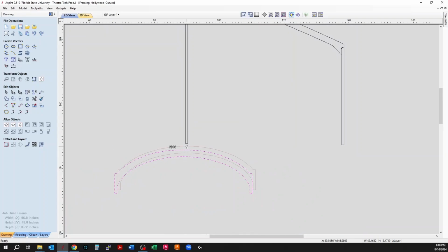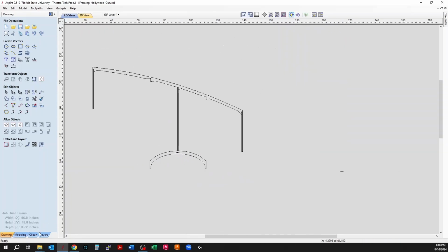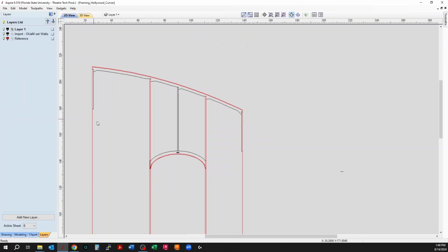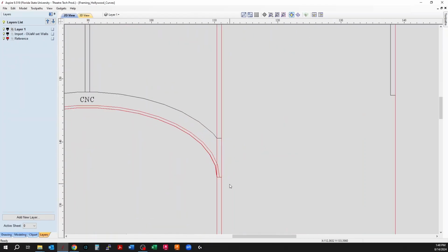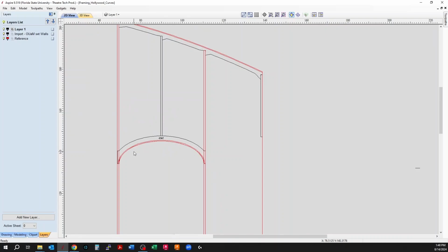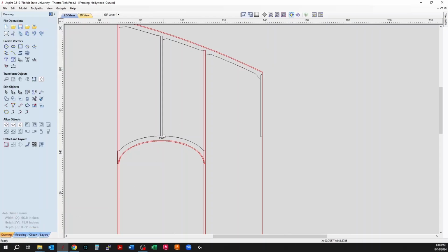So we'll grab that, put it right back where it's supposed to go, and so on. So now, if we look at our reference layer, again, we are intersecting through that, and then we'll have to dado out some notches on both sides of that to allow for that frame to interact. Last thing is I added this piece in the middle, so I can staple it pow right there.